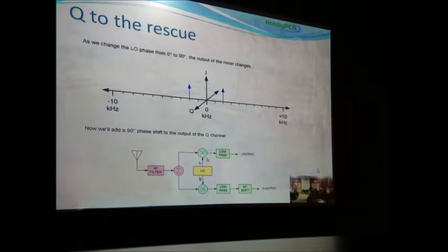It's actually implemented using digital switches, but these are all analog signals, except this last 90-degree phase shift. This last 90-degree phase shift happens in the digital signal processing, because that's actually the very difficult one to do. It's difficult to maintain a perfect 90-degree phase shift over 200 kilohertz of spectrum in analog, but it's pretty easy to do it in digital.